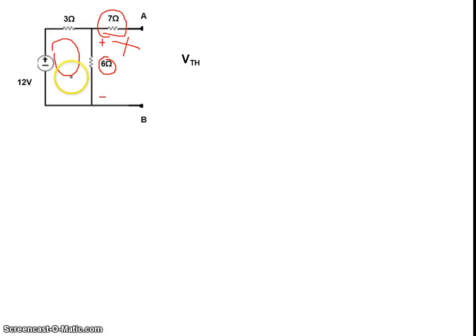Now that calculation is very simple here because we have a single voltage source and two resistors connected in series. So here what happens is a voltage division. The total voltage gets divided across the two resistors. Now if you want to find out the value of voltage across 6 ohm, the method will be total voltage multiplied with that resistance across which we need to find the value, divided by the total resistance. So let us do the calculation.